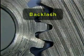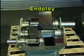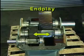Backlash is just one term that's commonly used when working with gears. Another one is end play. End play is the distance that a gear and shaft are allowed to move axially, or along the shaft axis.